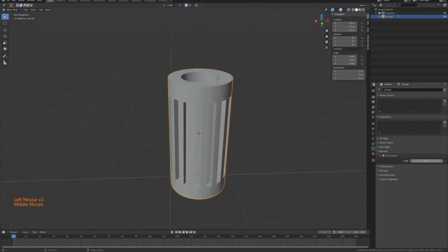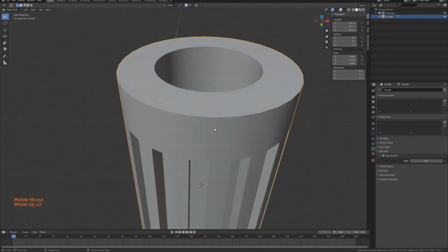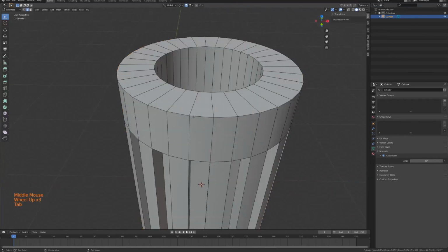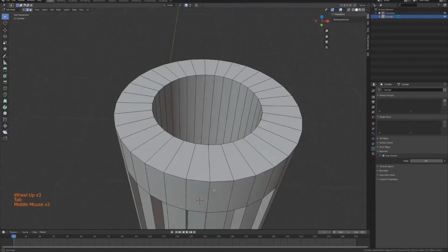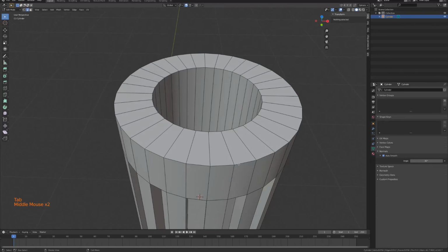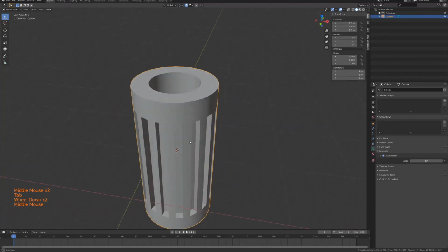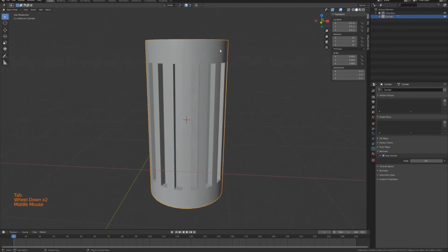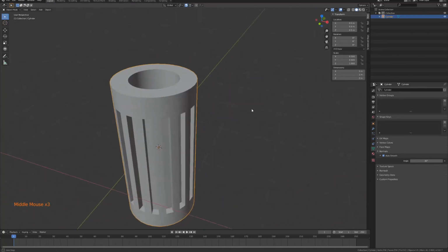You also have this angle property here. Changing the angle property will determine the maximum angle for smoothing. So in this case, because there is, for example, less than a 30-degree angle between this and this, it will smooth them into sort of a uniform shape.